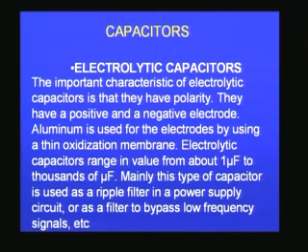If you interchange them, it will lead to some difficulty, because the current will flow in the opposite direction, and therefore it will evolve some gases, and finally it may also explode sometimes. So one has to be very careful when we use capacitors in the lab. You should make sure, especially with electrolytic capacitors, that you look for the plus and minus signs on the capacitors and connect them properly in the circuit with the right polarity.